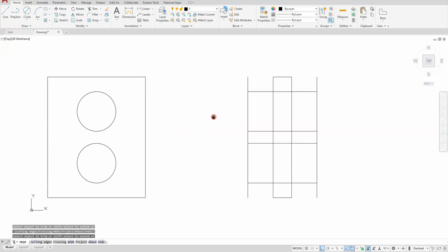The next thing I like to do is start working on my pegs. So I'm going to walk this line. I'll click here, and then I'll keep clicking these endpoints until I get to the desired location. I'll do the same here at the bottom. I know that my peg here at the bottom sticks out here. I'll start on the other side and walk this one up until I get to the desired position. And then I'll trim the top peg off there.